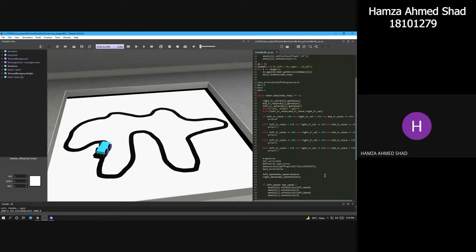Let's talk about the process of PID. The first step is that we put in some basic set points that the PID will first use. Then we do some basic computation from the feedback of the output. Then that output feedback is applied as an error to the PID. The proportional part of the PID is Kp times the error.